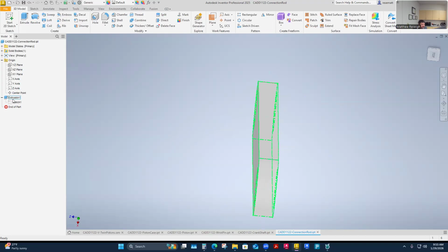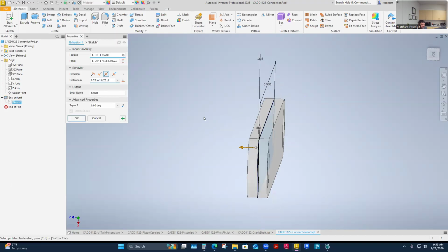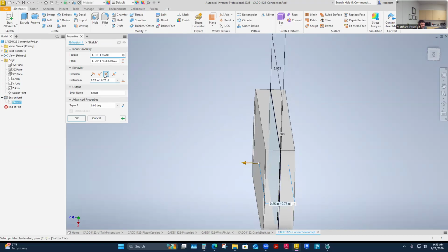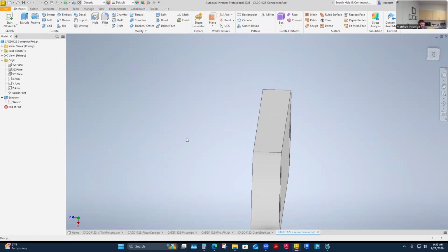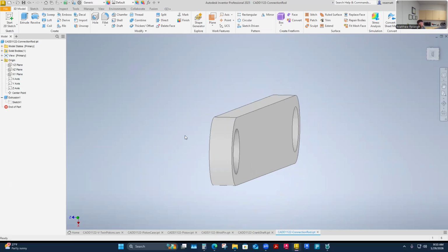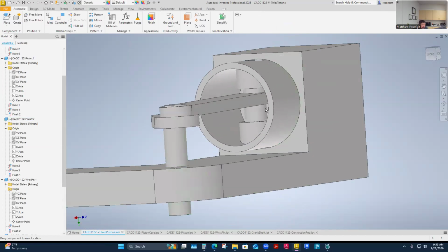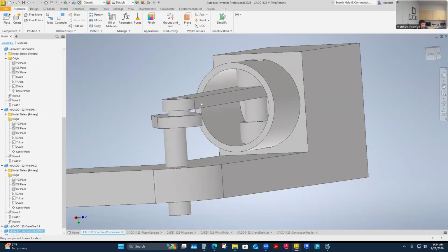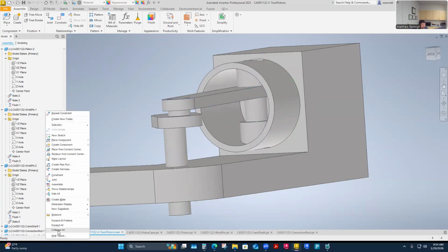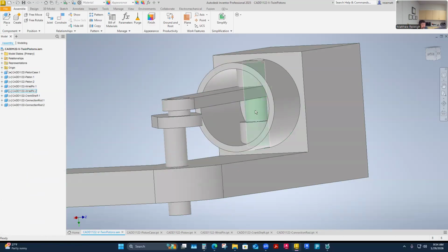So if you've made this extrusion, let me edit this feature. I've got mine extruding both sides of center. And this will help me use that plane to constrain on the centers. So I'll say okay. So make that change like you would on the wrist pin if you didn't do that. It'll make this assembly easier. Because the first one I'm going to do is lock it up so it's centered on that wrist pin. So it's really that same center line on this one, which is this one. That one right there. I'm going to line it with the center line on this one. So like I say, it helps to sometimes collapse all these things, collapse them, and then I can just pick the ones I want. Here's one.